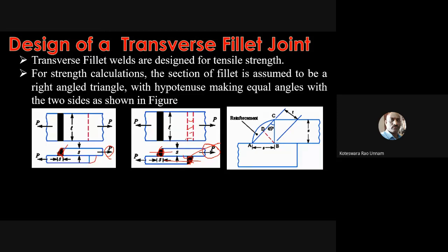So you can see from looking at the figure also what terminology or convention is being followed here. He has shown two dotted lines showing that there is a weld. Even this view is not available to you by looking at the top view. Here you can say that this is the weld, but here there is a single line, which means only this is the hidden line because of this edge. Here you have two hidden lines, which means you have a weld at this location also. Like that you can understand.